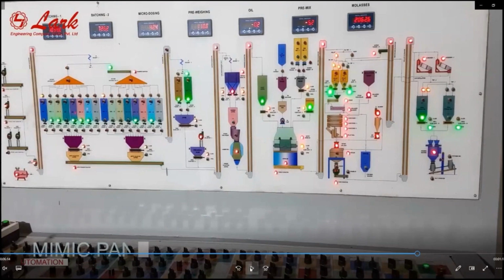So we did audits in feed mills. What we observed, not in each and every feed mill, but in a few feed mills, is that in the night shift the pellet operator generally runs the pellet mill at 80 or 85% efficiency to avoid the overflow of the cooler siren system. He wants to work freely, so he runs the pellet mill at 80-85% so that he does not have to run around. So in the plant performance analyzer module, you can have an idea which machine is running at what ampere,